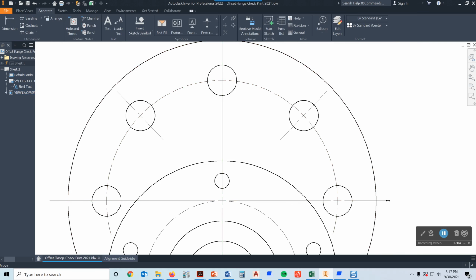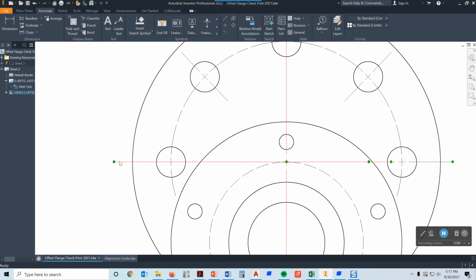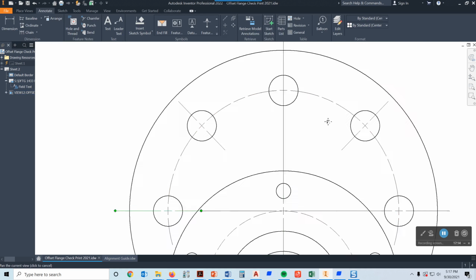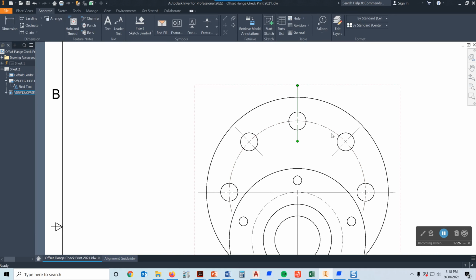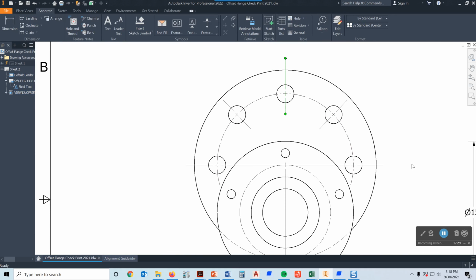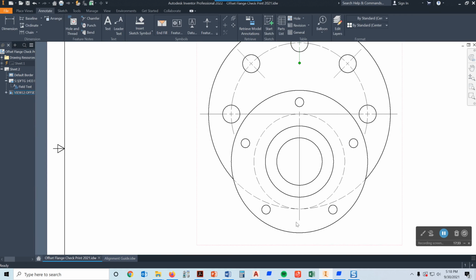And so now I want to drag this one out about 6 millimeters. I want to do the same thing over here, drag it all the way back so I can see 4 gaps right here, and drag this one out. And I've got the same thing going on right up here. I'm going to drag it back, and actually I'm going to have to put a center mark in here. So I'm going to drag that one all the way back. I'm going to bring this one out because it's on the y-axis and the x-axis. I'm bringing those out about 6 millimeters. Now this one in here, I'll probably also bring back, and you'll see why in just a second.